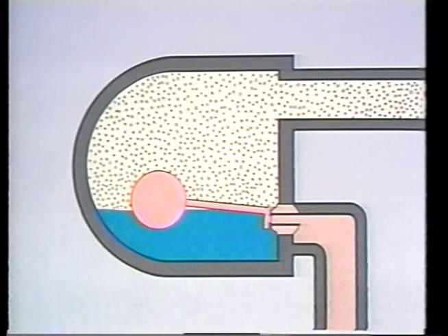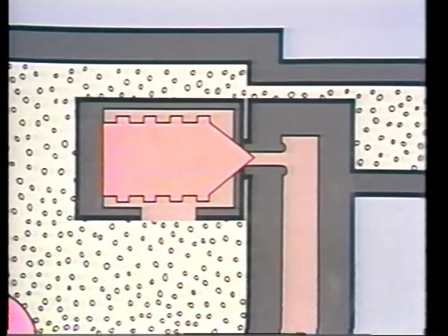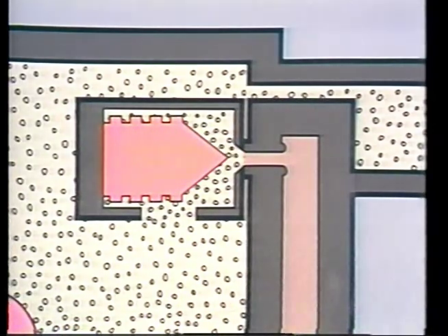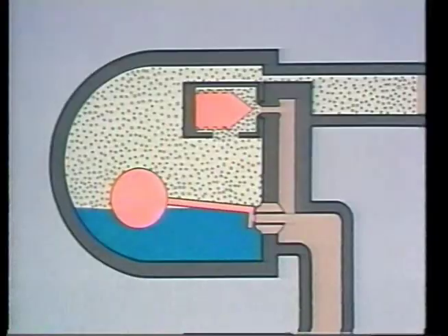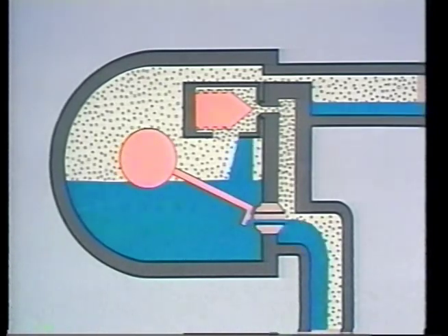Since some air is found in almost all steam systems, a lot of float traps have a thermostatic bellows inside to vent the air. These are known as F&T, or float and thermostatic traps. In this example, the bellows is located in front of the trap inlet. When air collects inside an F&T trap, the bellows will compress because air has less heat energy than steam or hot condensate. The compression of the bellows opens the vent valve, allowing air to leave the trap and allowing condensate to enter.